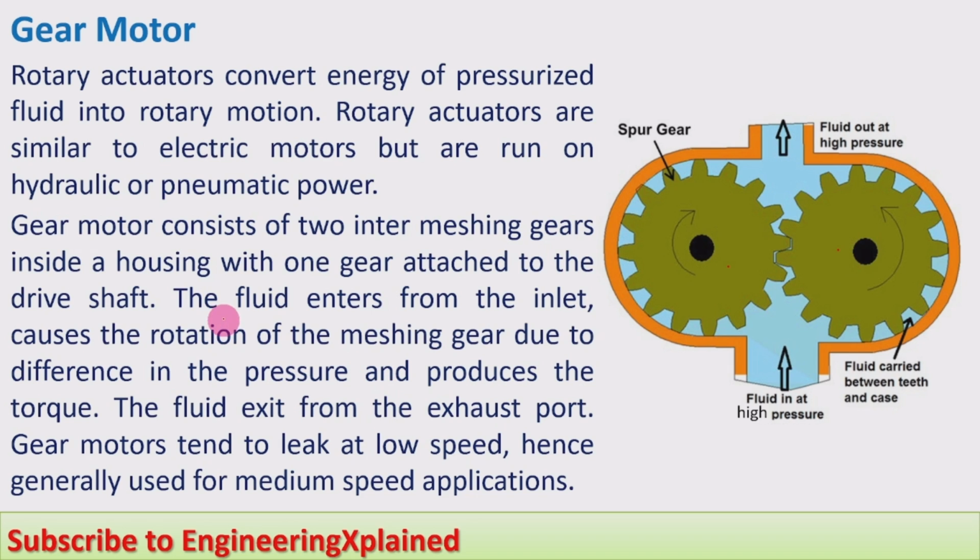Then here the fluid enters from the inlet and causes the rotation of the meshing gears. When it enters, it pressurizes the gear teeth. The pressure will be applied on both sides of the gears, and due to that the rotation of these gears will take place, with the fluid entering at a higher pressure.